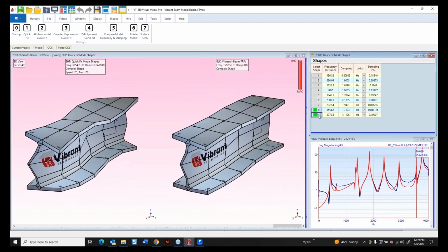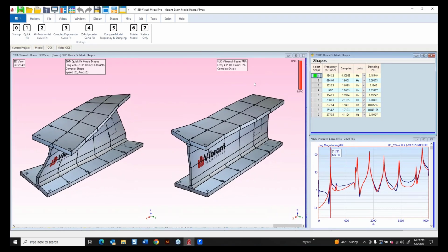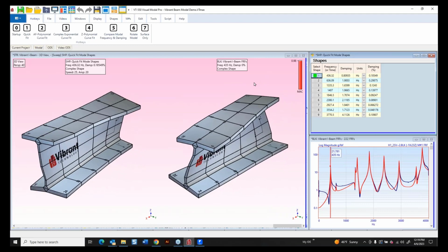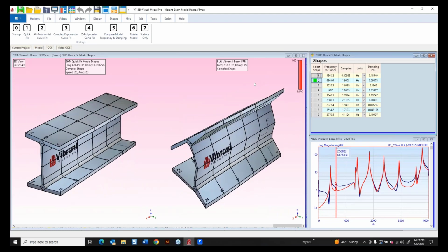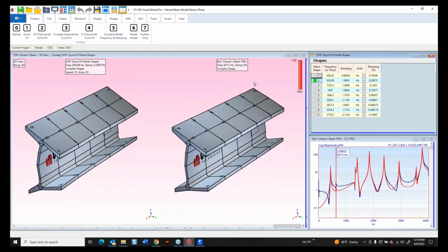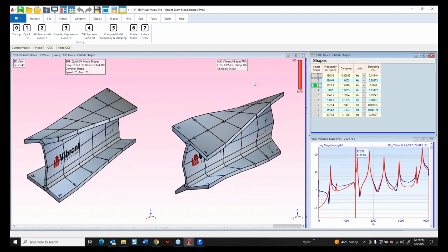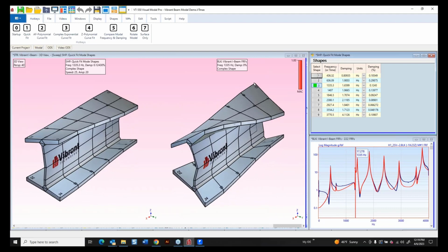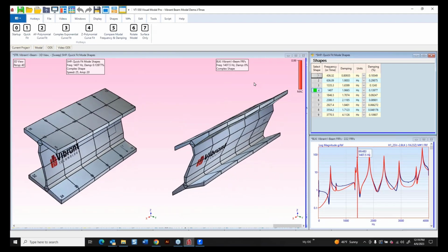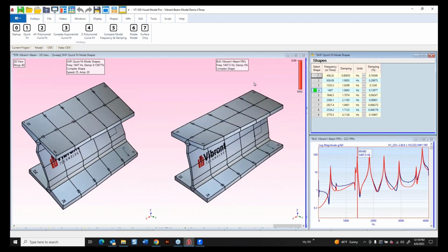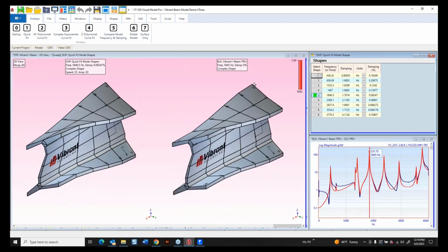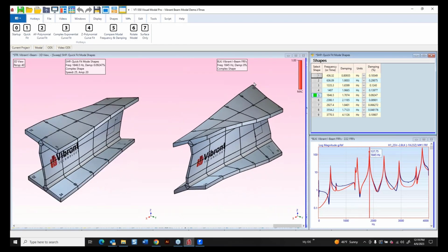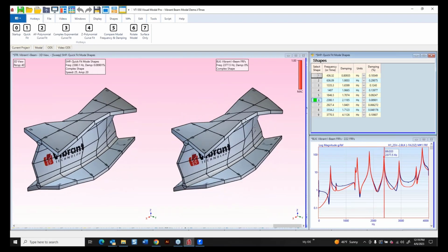So the ODS for lightly damped data is numerically different, but it's lying on the same straight line with the mode shape data. So MAC will tell us, are they the same shape? Do they lie on the same straight line? SDI will actually compare values and tell us whether 2 different curve fitters gave us exactly the same values.